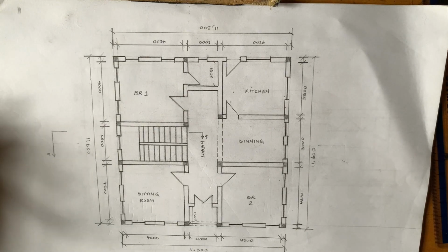Now after measuring for the concrete works, the next thing you're going to be measuring for is the formwork. Now the formwork is very easy to measure. It's either you're measuring it in linear meter or you're measuring it in meter square, depending on where the formwork is going to be placed.